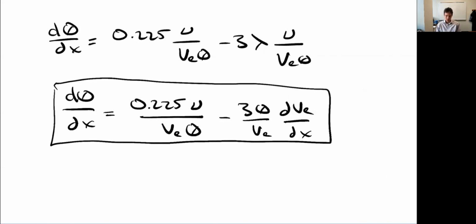So if we look at this equation, recall that the edge velocity is an input, right? We get that from our inviscid solution. So if we're solving for the flow around some geometry, we've already computed what the edge velocity is everywhere around that. That's the tangential velocity around the geometry from our inviscid solution. Because we know V_E, we can also get this derivative. And remember, we're using boundary layer coordinates, so x just follows that curvature. It's just how does the edge velocity change as we go around the boundary layer. So these are all inputs, and ν is an input as well, often in the form of a Reynolds number. So this is just an ODE that we can solve for theta using any of our favorite ODE solvers.